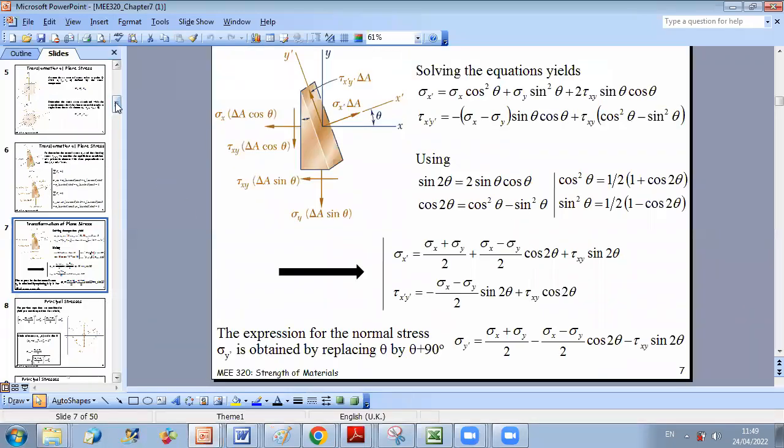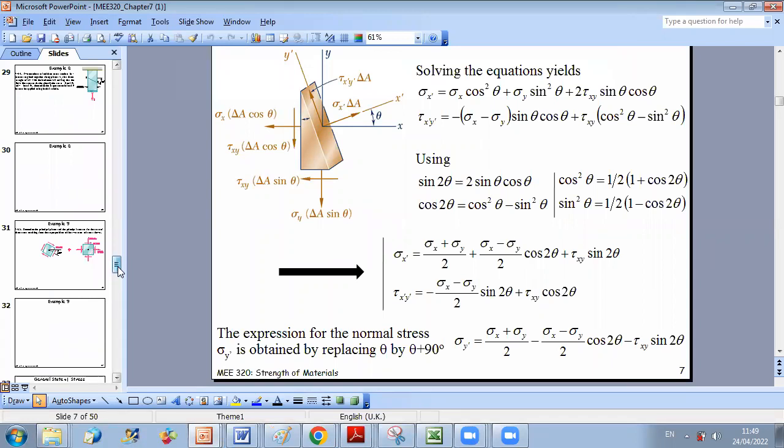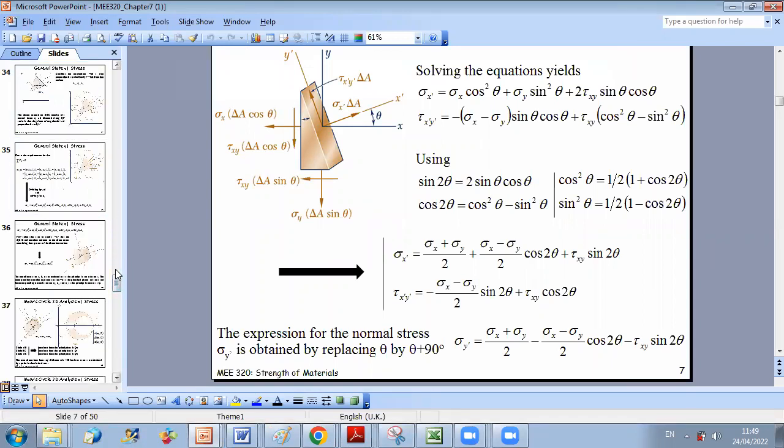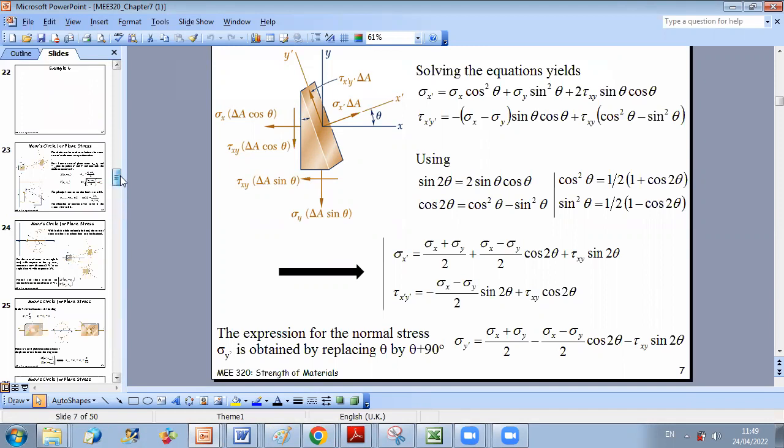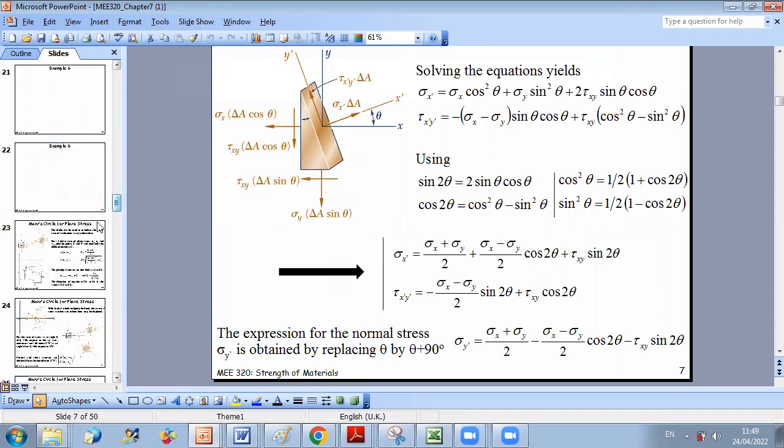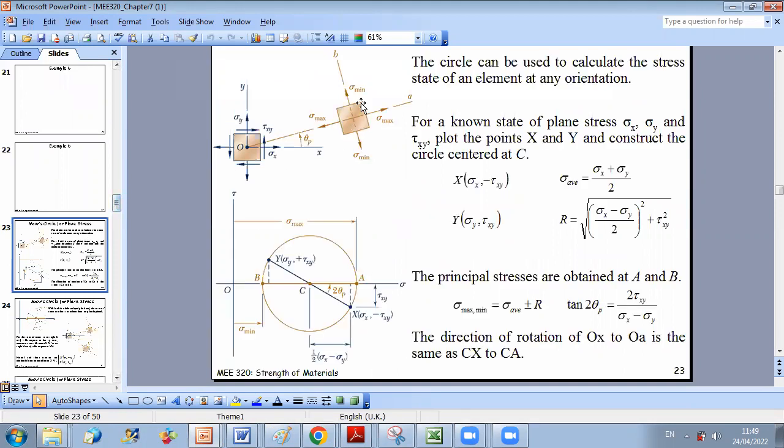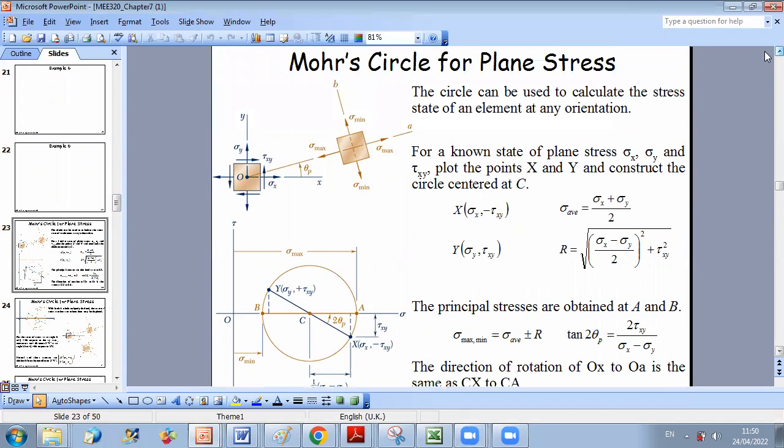Okay, so going back now to the course material, as we said, we will go over how to draw the Mohr circle and how it can help us get the state of stress in any direction we want. So until now, we have considered 2D stresses, and we said that once we know the state of stress in one frame XY, we can deduce the minimum and the maximum principal stresses, and we can deduce the maximum shear. Now, what about any other direction?